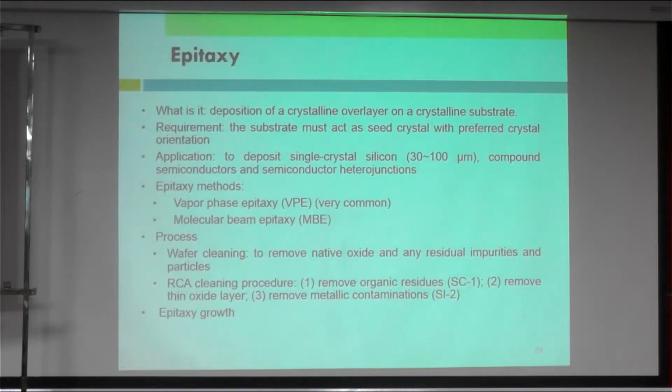So next we will look into epitaxy. What is epitaxy? Epitaxy is deposition of a crystalline overlayer on a crystalline substrate. Basically, we try to deposit material layer by layer. The requirement is that the substrate must act as a seed crystal, with a preferred crystal orientation. So the layer needs to have a seed. An application is to deposit single crystal silicon, for example 30 to 100 micrometers, compound semiconductors and semiconductor heterojunctions.